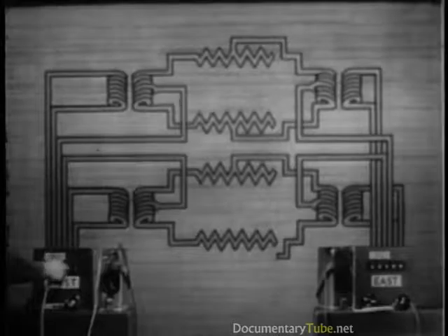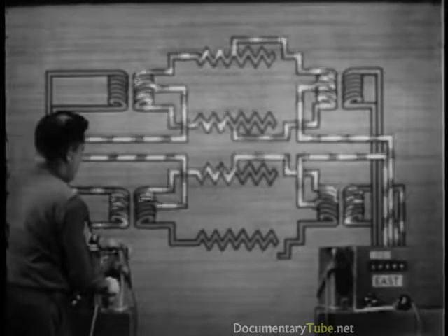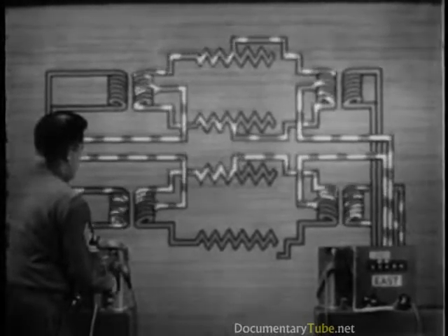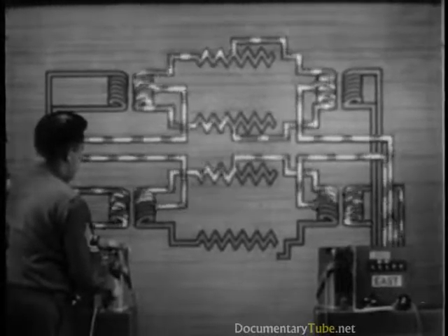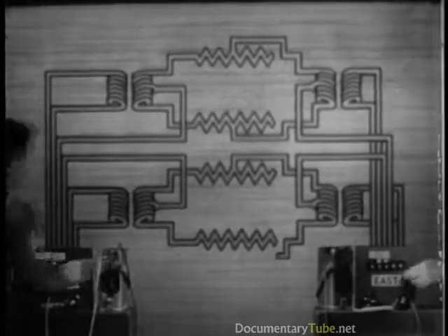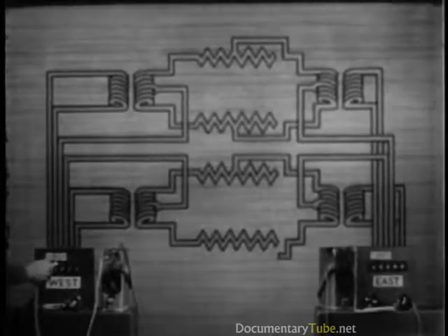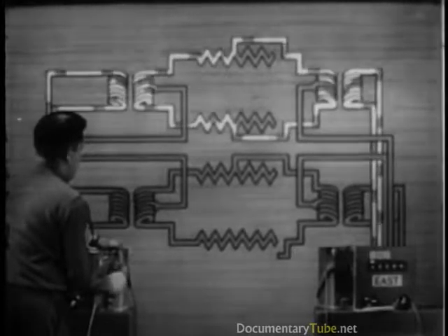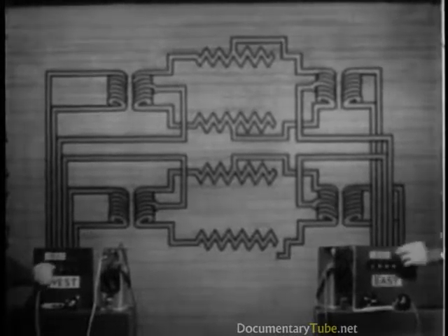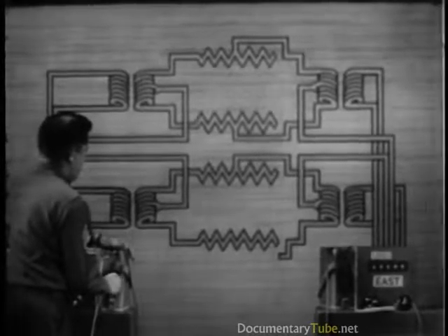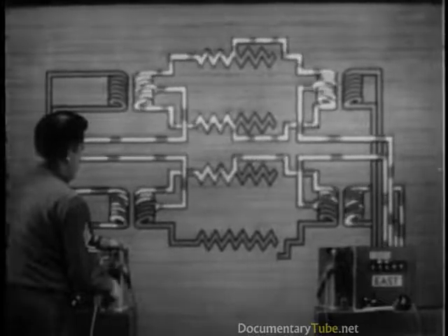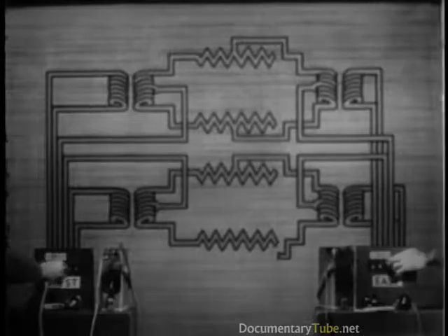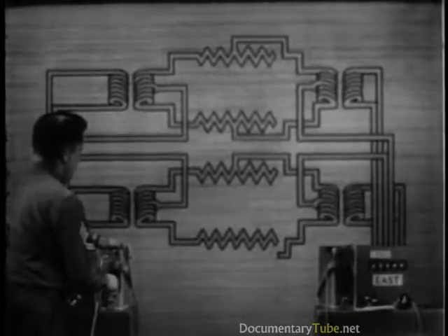Ringing on the faulty side circuit produces a weak current, which finds a return path through the phantom. This causes interference in the phantom. The unbroken side circuit operates as usual. The phantom interferes with the open side circuit and the open side circuit interferes with the phantom.